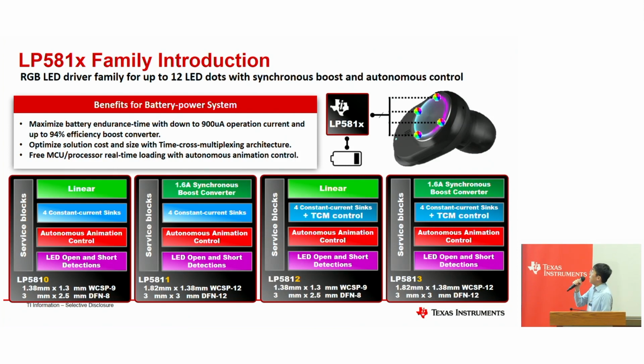So this LP581X device family is an RGB LED driver supporting up to 12 LED dots, and it is integrated with a synchronous boost to accommodate battery-powered products, and it also has autonomous animation controls to release the bus load on MCUs. So some main benefits for those battery-powered systems.